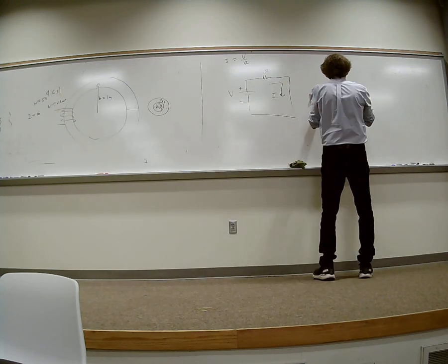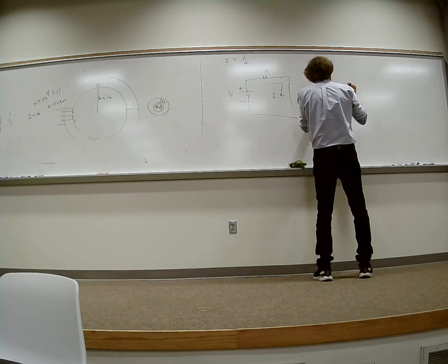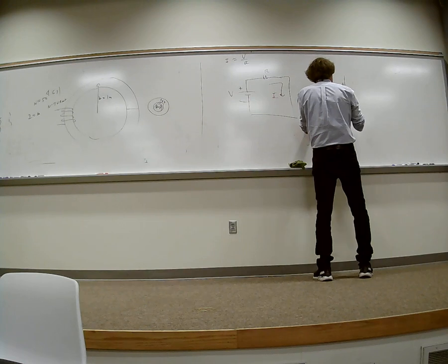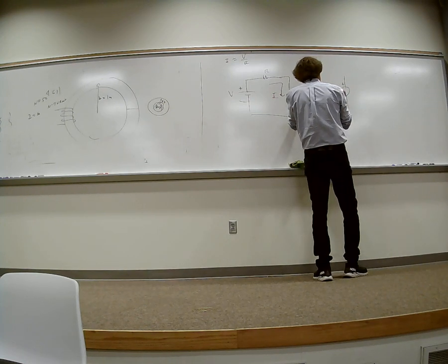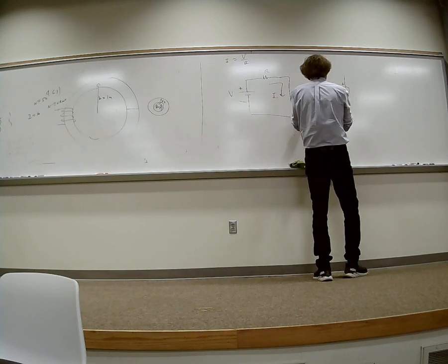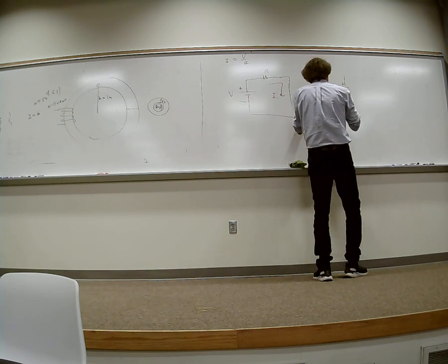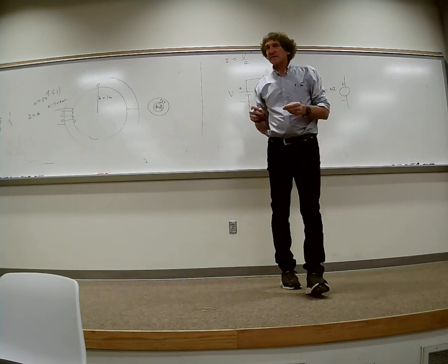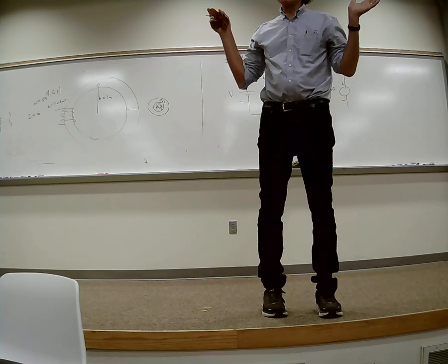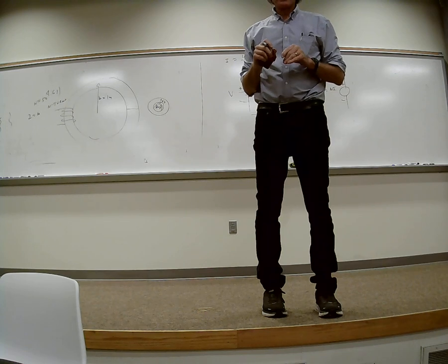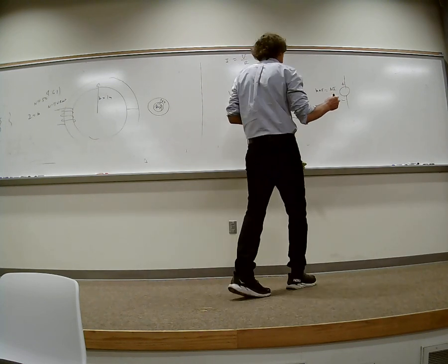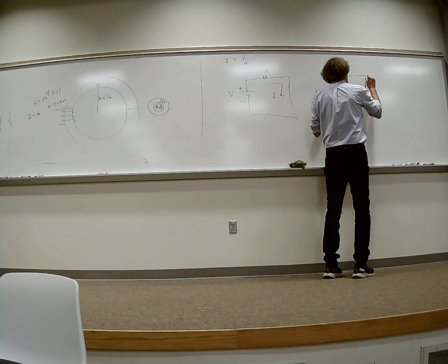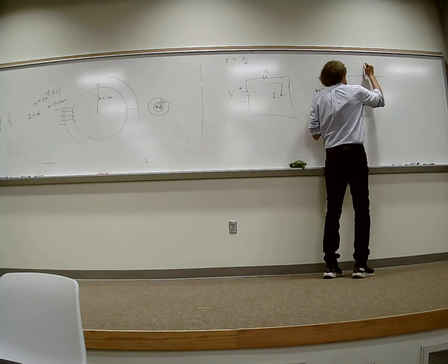Now here is an equivalent magnetic circuit. Instead of a voltage, you will have something called MMF, magnetomotive force. So here, the MMF is equal to N times I. Think of N times I as a voltage, a magnetic voltage, if you will. Now, the next thing you have over here is something called reluctance, not resistance. The symbol in the book is this for reluctance.